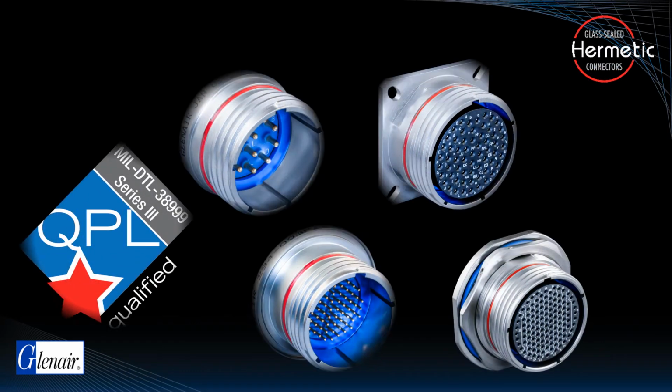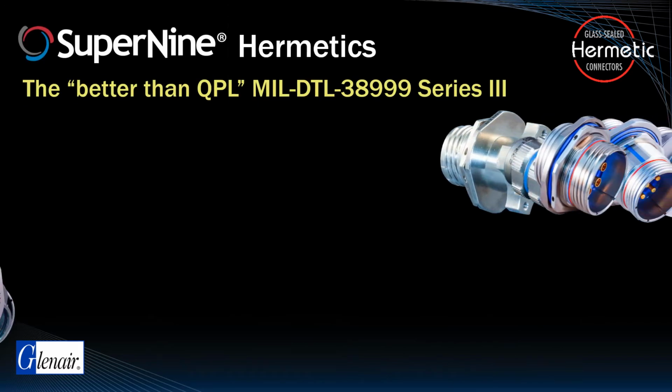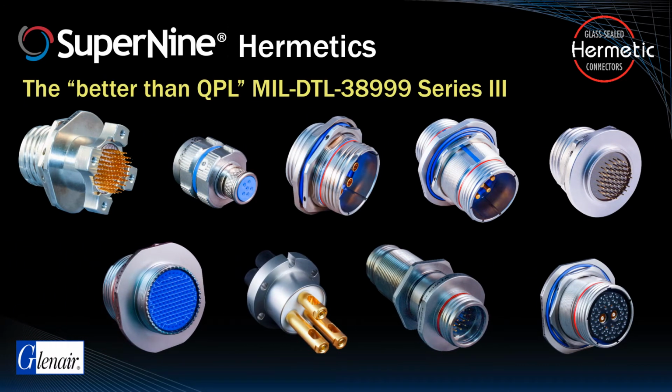The glass-to-metal sealed MIL-DTL 38999 Series 3 is by far the most popular hermetic connector in current use in military, defense and aerospace applications. Glenair offers QPL hermetic connectors in this series, as well as a special better than QPL derivative with significant improvements in durability, vibration and shock resistance, EMI shielding, as well as a significantly broader range of shell modifications and wire termination options.